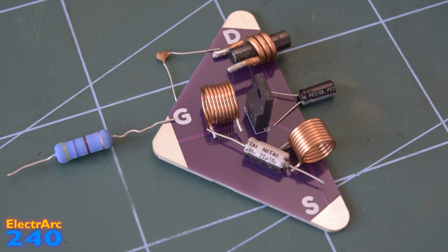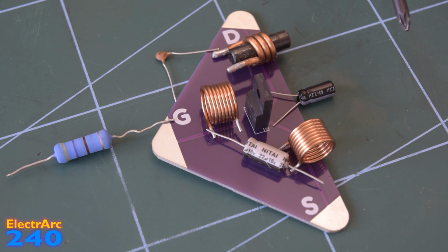I'm now going to really quickly run through a few strategies that you should keep in mind to try and reduce the effect of these parasitics. There's something called soft switching, which is basically where you turn the MOSFET on and off, either when there's 0 voltage across it or 0 current flowing through it. This effectively means you have 0 switching loss, and the effects of a lot of the parasitics simply don't exist. It's a very cool thing, but unfortunately it's quite complicated to control and very difficult to implement in some topologies.